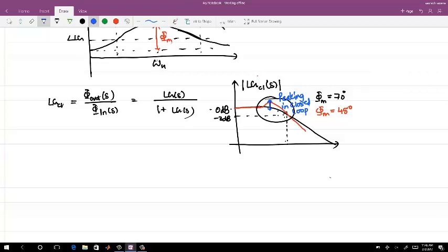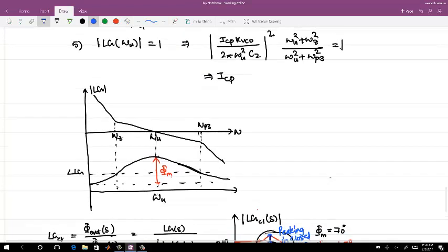And the other thing is that right now I have not shown any noise characteristics. If there is a peaking in the frequency response, all the noise sources which are closer to the input, such as the PFD, the reference noise, or the charge pump noise, will be amplified. So peaking will at some point also lead to increased noise in the system.